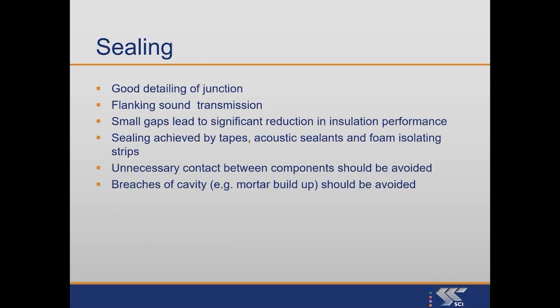And then the third point that I had on the 2 slides previously was about sealing. So that's all about junctions, and making sure that there's no sound air gaps, obviously, using acoustic sealant, acoustic filler and filler materials between hard surfaces, so sort of where a wallboard may meet the floor. You'd want to try and keep that junction sort of soft, so you don't have hard surfaces in contact, and that can be done with acoustic sealant or special foam strips and that sort of thing.